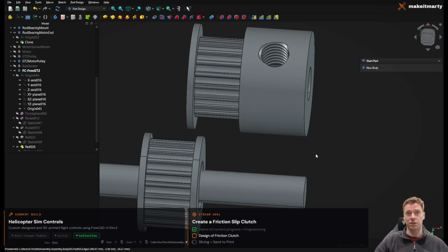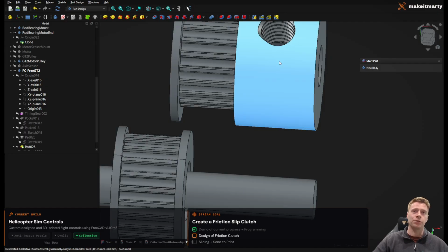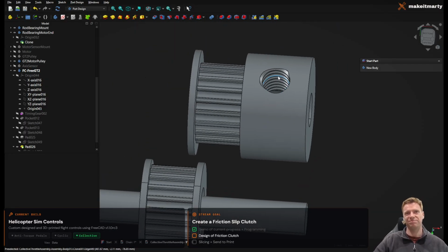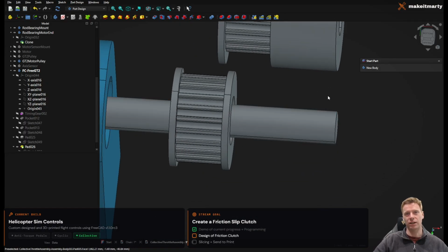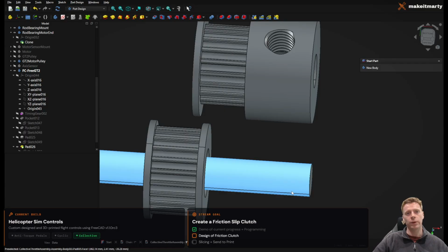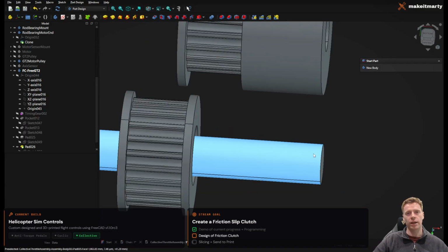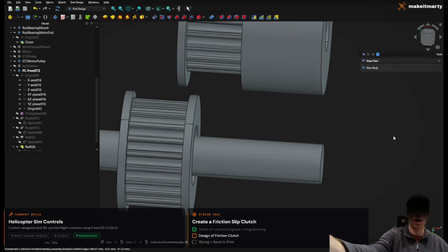I guess you can start to tweak the 3D layer heights and then nozzle diameter. Anyway, if you go smaller than that with a 0.2 mil layer height, the threads you get aren't great. So what we could do on this one is we could do a thread insert,